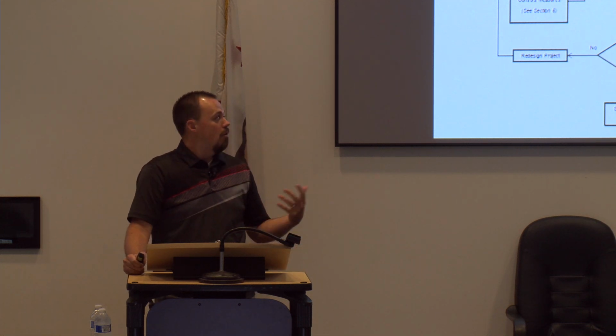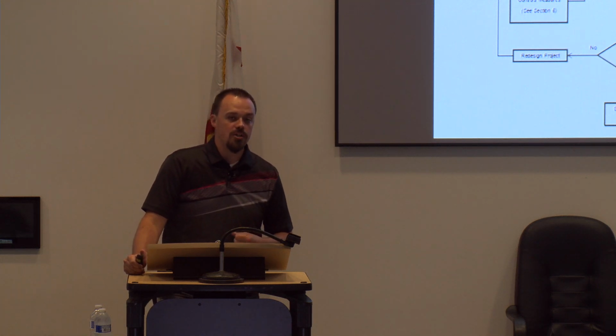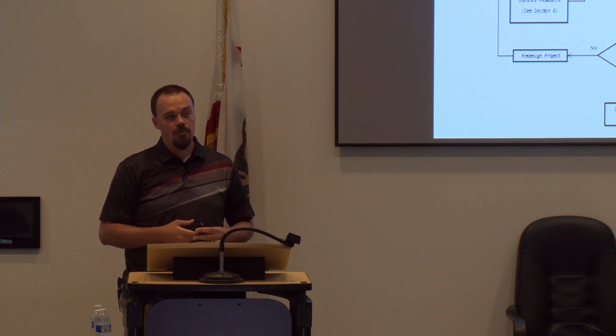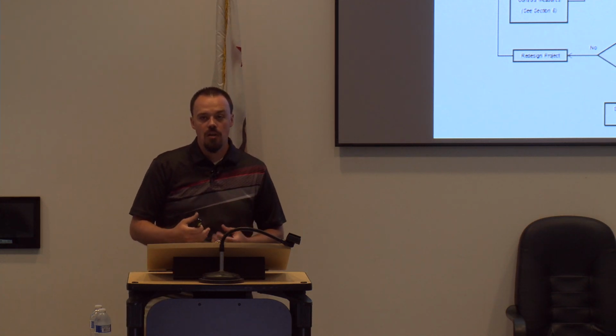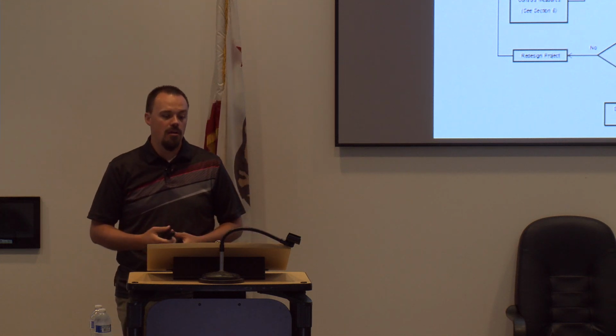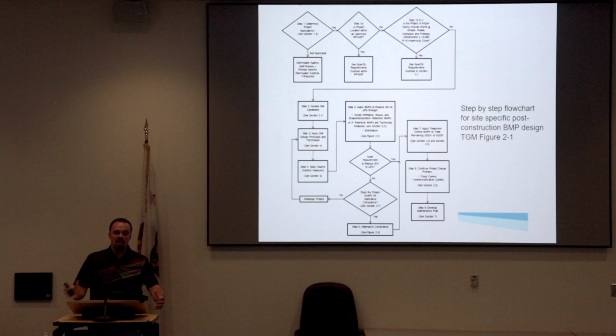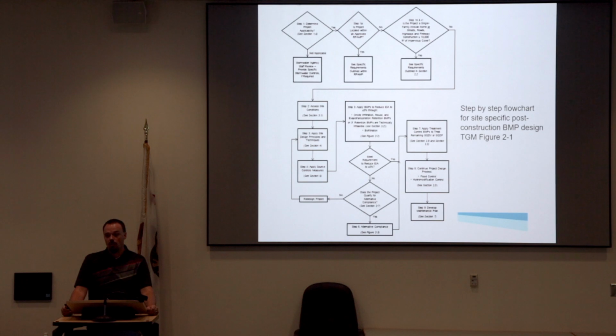What that really is, it requires certain projects, if you're located upstream of susceptible water bodies that are natural channels that are susceptible to erosion, things like that. So it's not an engineered concrete channel or something like that, where hydromodification and reshaping of that water body based on excessive amounts of water down it would require additional BMP sizing. So right now the general design criteria is about the first 3/4 of an inch of rainfall on a site you need to retain. With hydromodification, that goes up to about the 95th percentile storm in general. So it could be significantly a lot more water depending on where your site is.